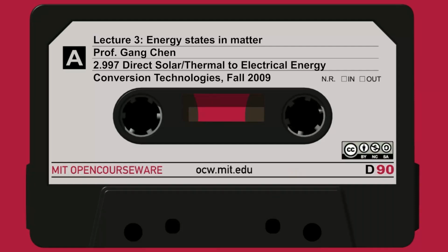Then it needs a lot of energy, right? It depends on the difference of the energy here and here. If this difference is very large, you get an insulator. Electron cannot move. So this, from the topmost of the electron to the next empty state, that's the band gap. Okay? And if this band gap is very large, that's an insulator. How large is large? A few electron volts.